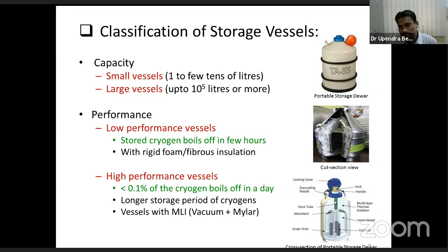But one thing one has to remember, an important point, is that in all these dewars, or these small portable dewars, the inner container is supported only from the neck of the outer container. And in between these two, we use a fiberglass neck or fiberglass tube for joining the inner container to the outer container, so that heat transfer is minimum. And of course, you have slits with this cork, so that some amount of vapor generated from this liquid because of heat transfer escapes easily. We cannot completely isolate or stop the heat transfer to the cryogen. So this gives the detailed construction of a portable container.